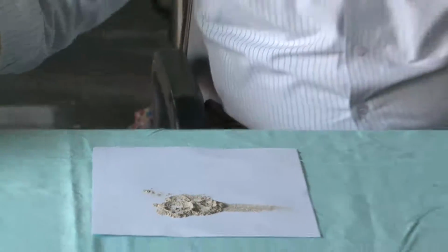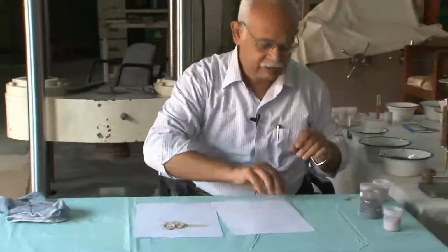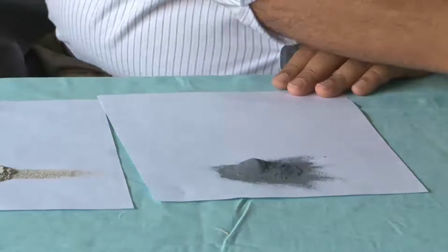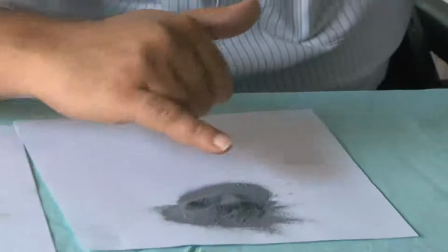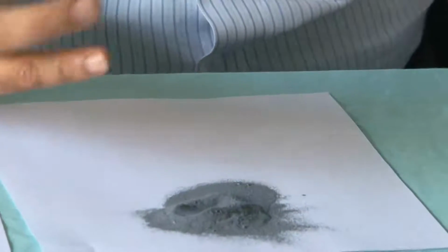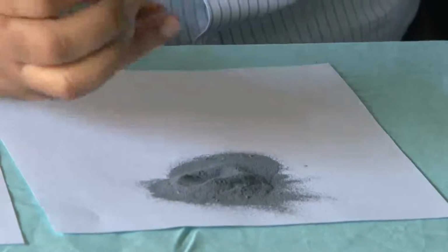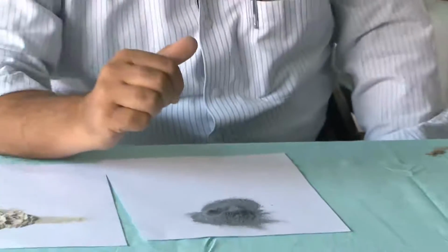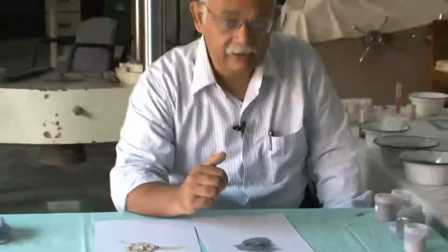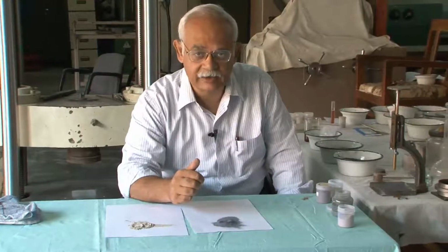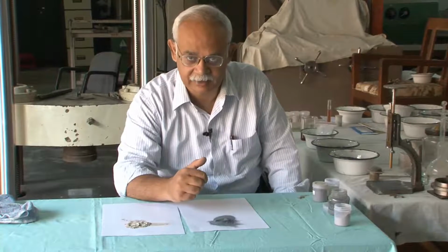As we have fly ash, there is also silica fume, and if we look at silica fume, this is what it looks like. This powder is difficult to see, but if you have a chance, please take a look and you will realize that the fineness of this powder is much higher. Typically, silica fume has the fineness of about 1/10 of normal cement.